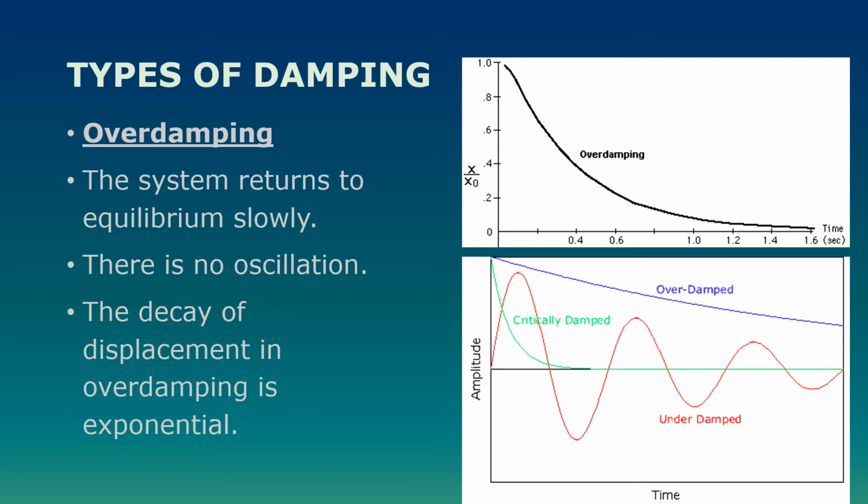There are times where critical damping and overdamping are a problem. For example, in a car suspension, there's a valuable example to look at in terms of damping. If you don't damp it enough, then the car, when it goes over a bump, will just continue to bounce. So you need heavier damping than that. But if you overdamp it too much, it won't return to equilibrium quickly, and if it's too close to critical damping, it can be quite a sharp jerk to equilibrium, which would be an uncomfortable ride. So it's about getting that balance correct for each different context we're looking at.